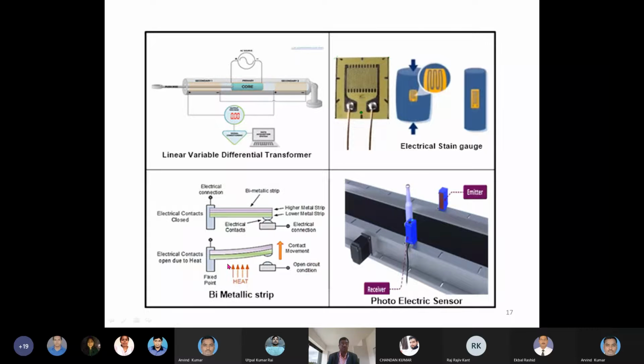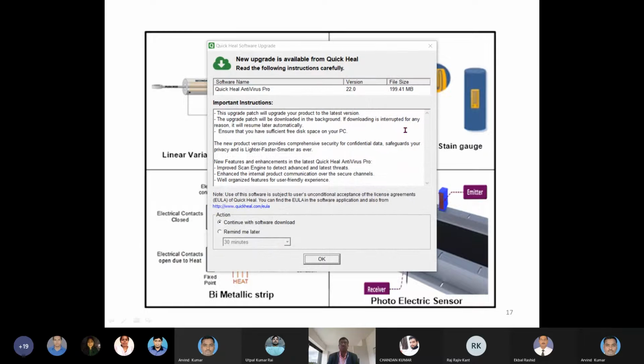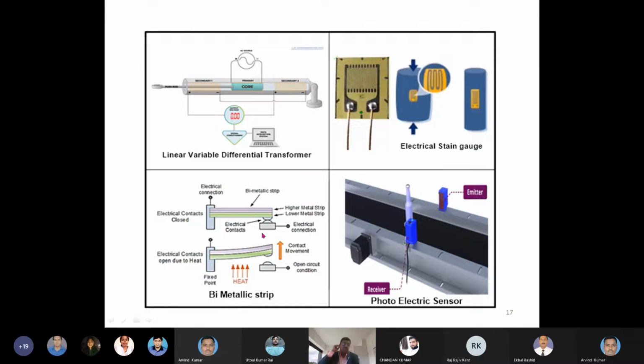So this bimetallic strip is used to monitor the temperature and accordingly take appropriate action. It will only take an action either to make the contact or break the contact. When the heat level becomes low, it makes the contact. When the heat level is higher, it breaks the contact. We commonly use this in an electric iron box: whenever it heats up, the current supplied to the heater of the electric iron is automatically cut off.